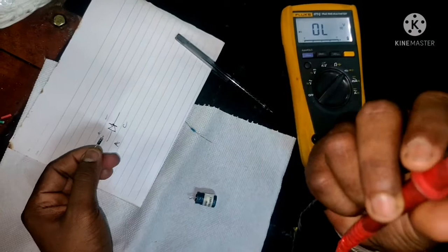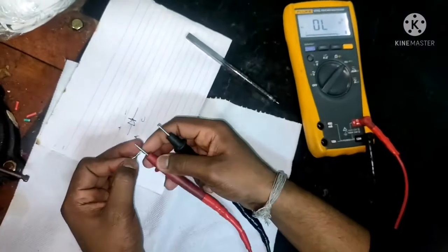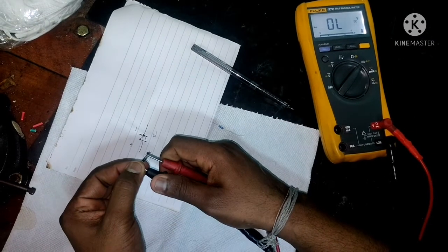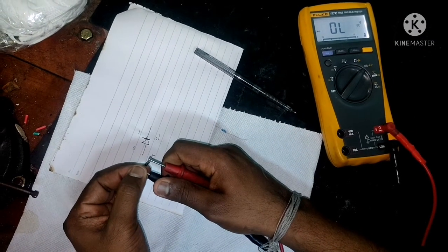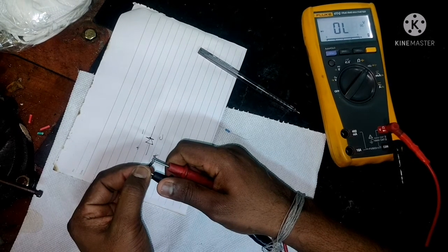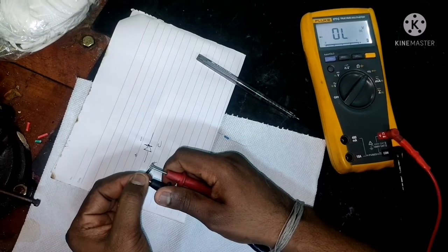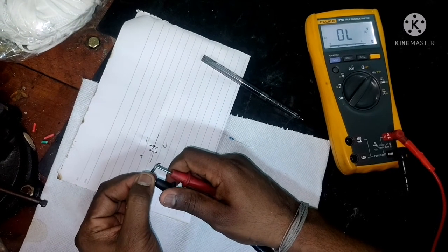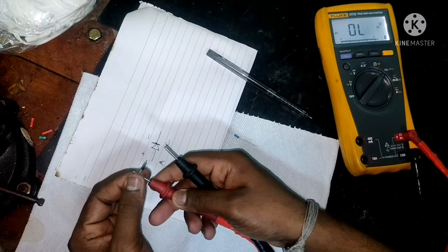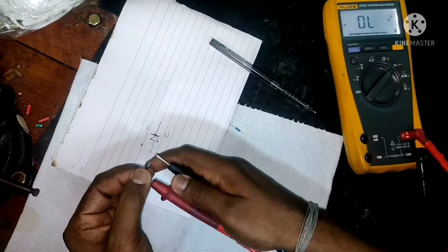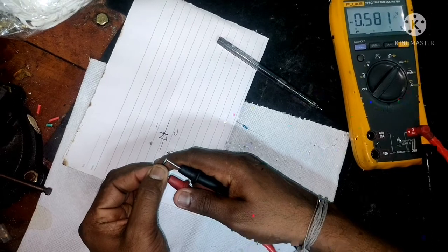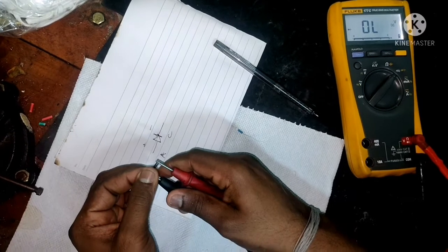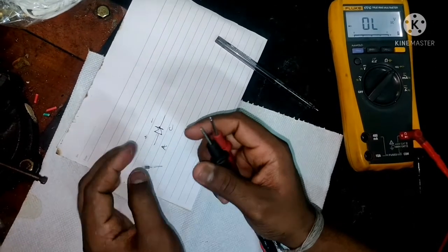So this is your voltage drop. This diode is unidirectional, so the current can flow only in one direction, and if I keep the leads the opposite way, you find no reading on the monitor. So all you need to do is connect your leads properly to the diode for checking the voltage drop. Red should be on the positive and black should be on the negative side, so you can find the value of the diode. If you put it the opposite way, you don't find any value.